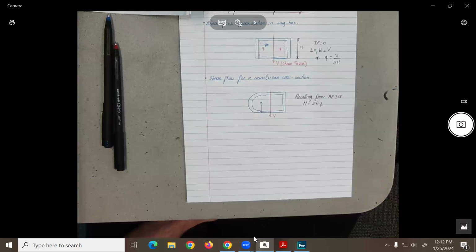Statically determined means a structure that is stable, essentially. The other one is also going to be stable, but basically, statically determinate means that you can find all the unknowns just by looking at the static equations. Now, what do you think statically indeterminate means? That the static equations of equilibrium are not sufficient in order to solve the problem.